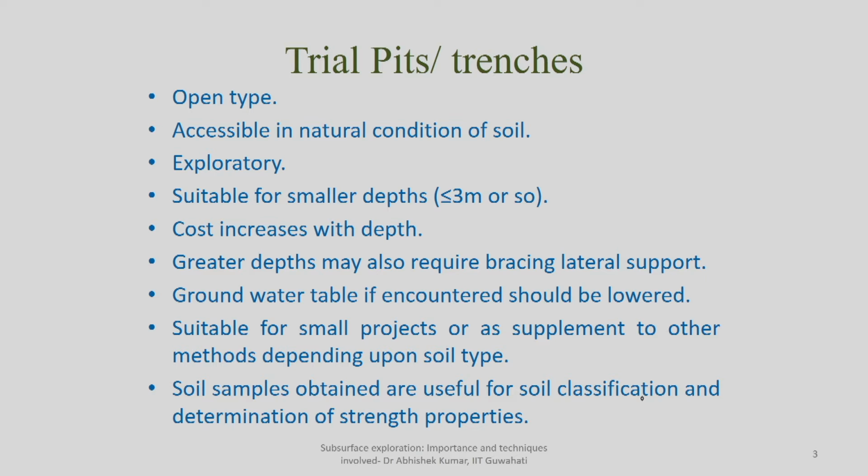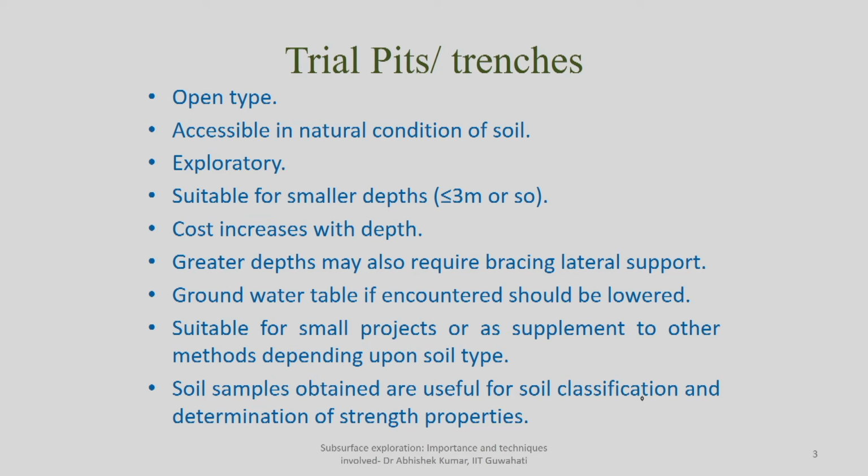Then the soil sample, as I mentioned earlier also, because you go to the site and you actually dig, every time you are digging the soil, you will get a big chunk. So, those samples can also be used for soil classification at that particular depth, in terms of grain size distribution, in terms of hydrometer test and so on, and then for determination of shear strength properties. So, whatever soil you are getting from trial pits or trenches, you can use it for classifying the soil, and you can also use it for determination of shear strength properties, because the soil you are getting is more or less in the same intact condition as it was at the actual site of interest. You are actually bringing a chunk of it, so it is a significant mass. If within the mass you take some smaller samples, the moisture content and other parameters will remain intact as they were in natural condition. So, you can use it for detailed testing.